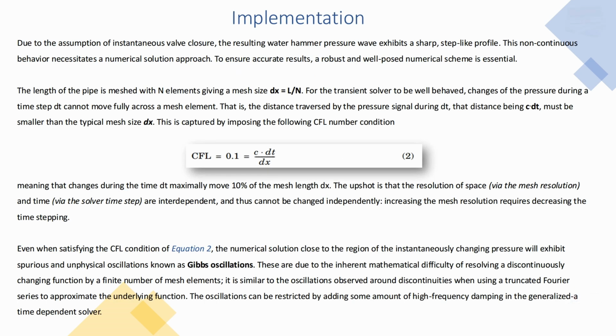The Courant-Friedrichs-Lewy condition, CFL, and the potential for Gibbs oscillations are important considerations when numerically simulating water hammer events.